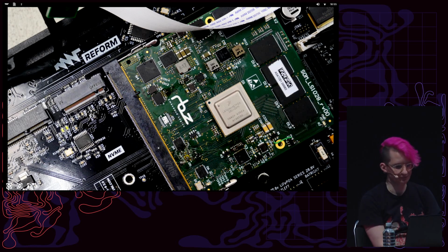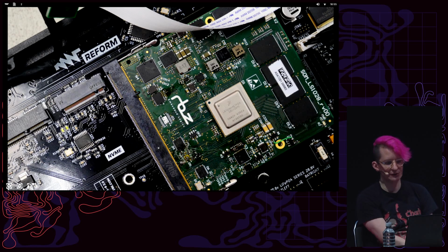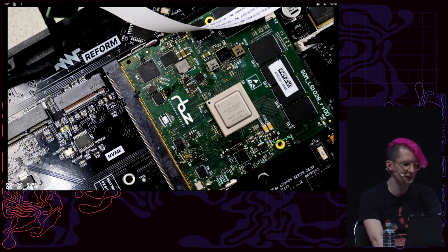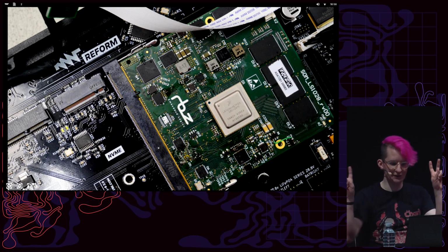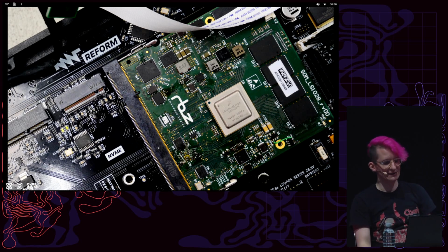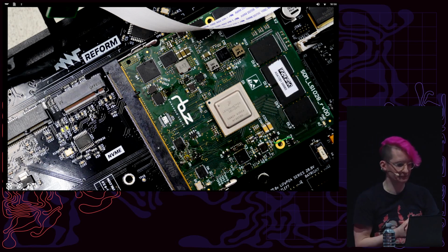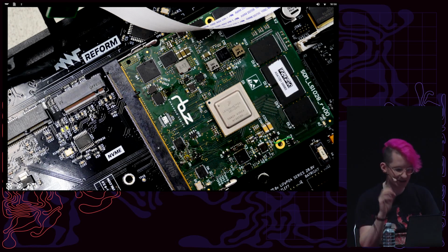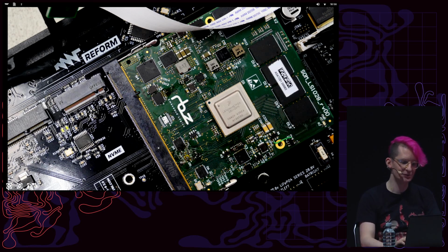For example, when we were finally ready producing the first batch of the boards, the processors were completely gone from the market. And lead time was almost a year. Only with luck and a contact at NXP, we were able to get a shipment of strategic samples that were not listed anywhere. Then the boards did not boot most of the time. Nobody, including NXP, knew why. I then found out weeks later it was because of a floating JTAG reset pin that I had to hand fix by soldering on all the production modules.